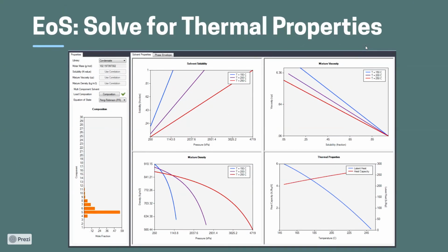Thermosolvent. This is really problematic for a lot of reservoir engineers and production engineers to model, because in solvent applications and thermal environments, it's not just solubility and viscosity that you have to match. You also have to capture the density, the mixture effects and mixture density, and also the thermal properties of solvents really accurately. You have to use some of it through the equation of states and some of it through experimental testing.